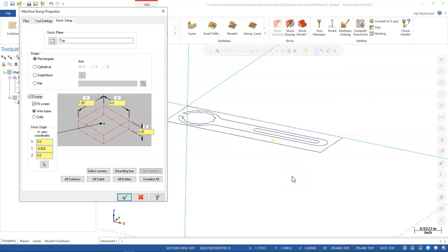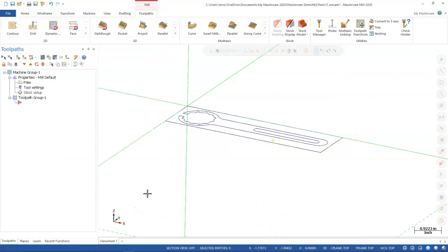Don't do that unless you have a really good reason. Certain machines have vacuum chucks, and you don't want to break into that base. If you see a negative value, you know that something's wrong, because you're going to break that suction. You're going to break that holding power. So that's one of the reasons we always did it on the router.